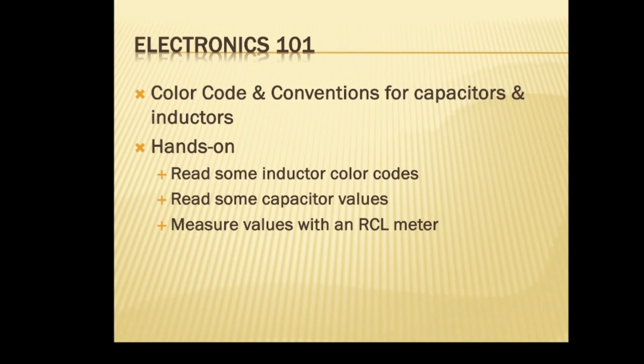But just to look at it, if I didn't know this was a resistor, I probably wouldn't be able to tell you that. I could probably guess at it. I look at that and say, okay, that's a 470K, so that's probably a resistor, because you wouldn't see a 470K inductor on that size. So that's the idea behind it.